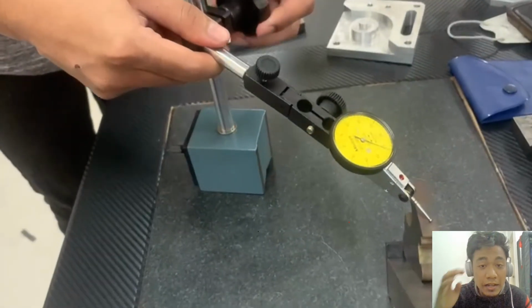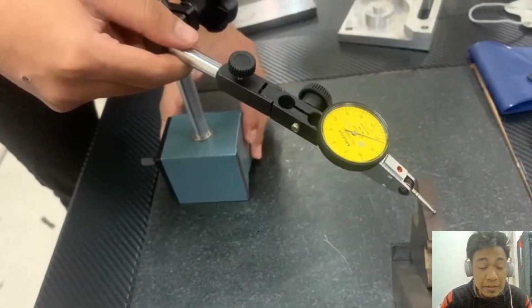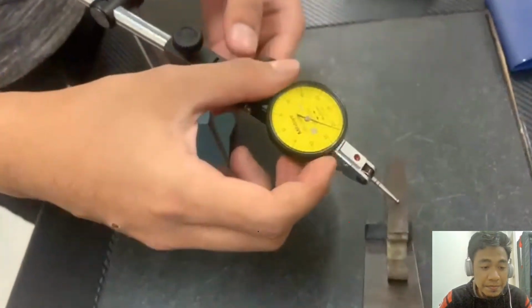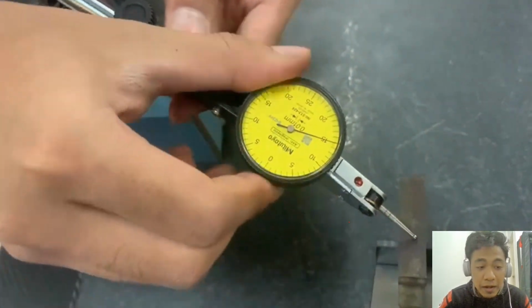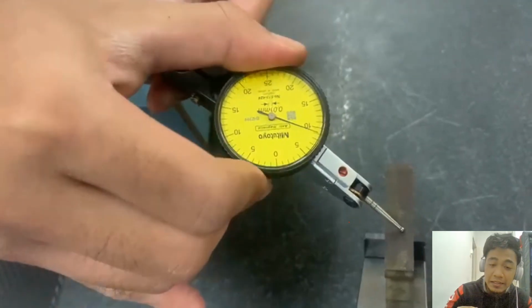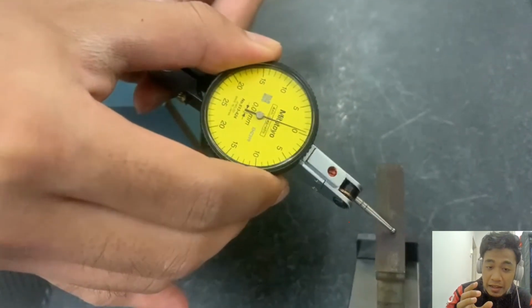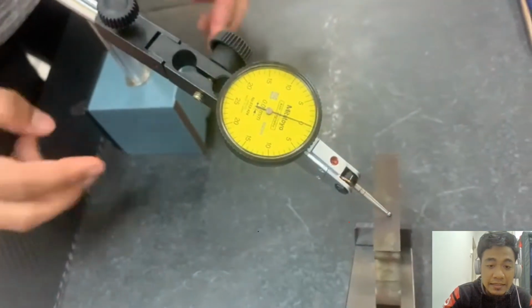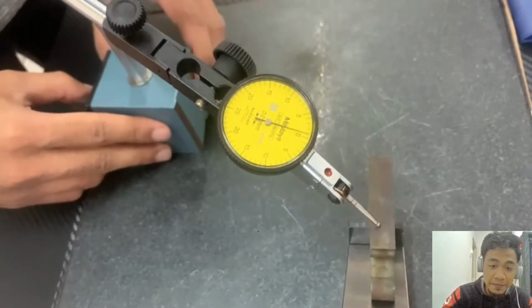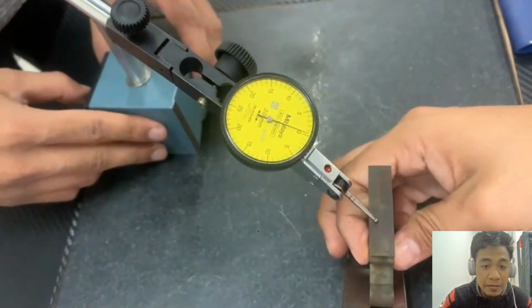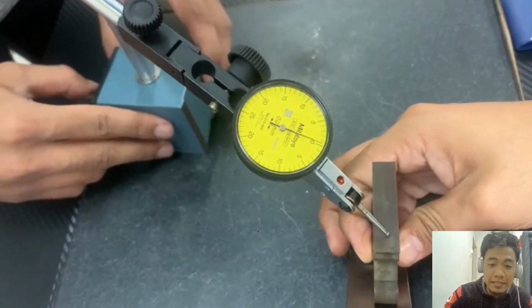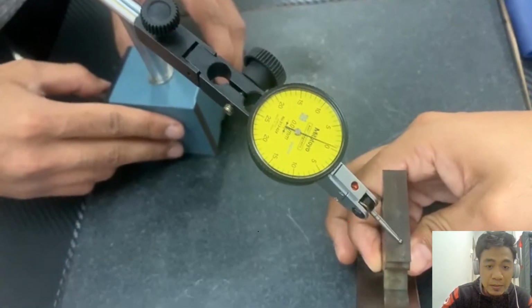We are measuring using the dial gauge. Basically, what are we doing here? We take the dial gauge and push it in a little. We don't put it only above, but push it in a little. After that, we set the gauge to 0. Then we need to move it front and back. You can see our part is moving, so we need to hold it. We are checking this front and back.